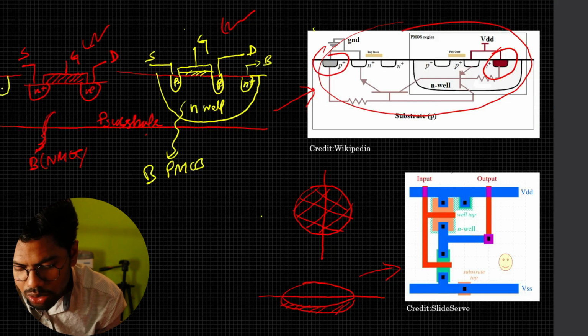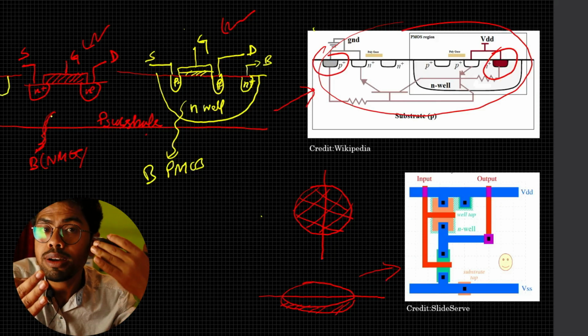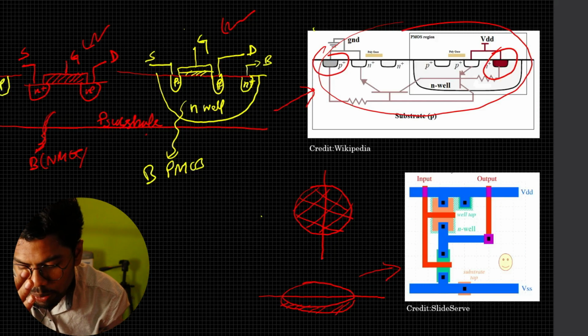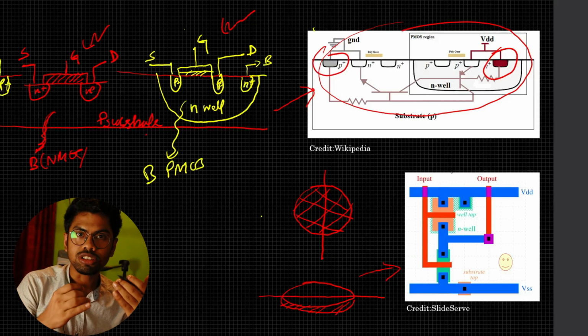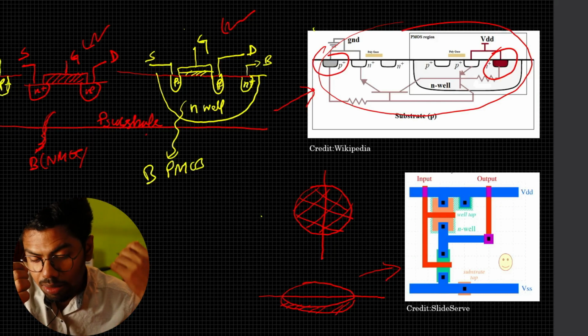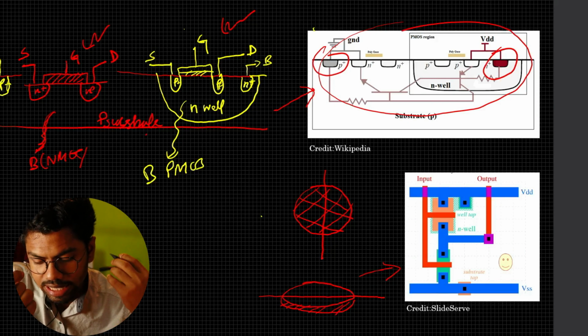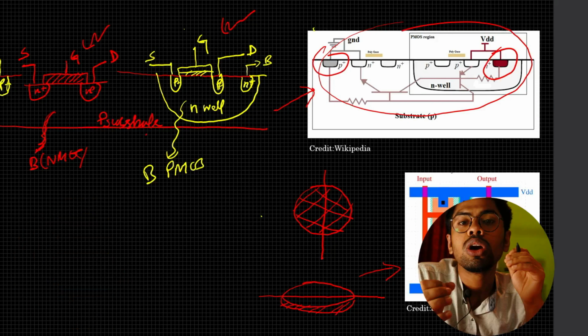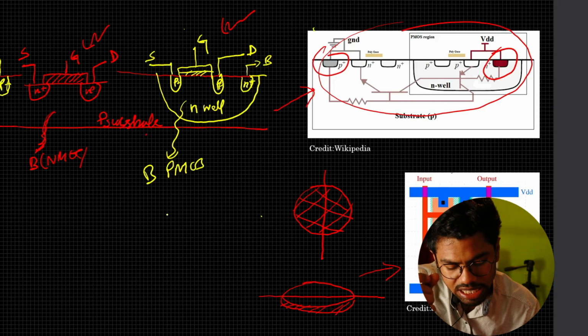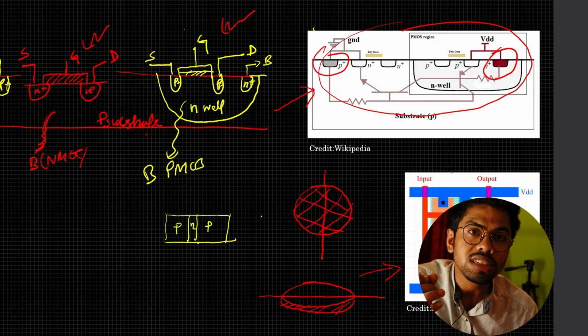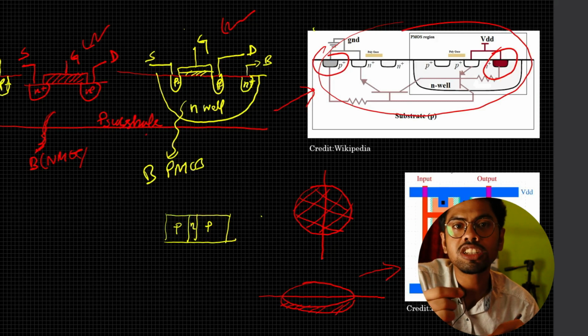And here also we do the same, because NMOS has a P type body, so we do P plus doping here, and we call it the body for our NMOS. Now if you look more closely, you can see one thing: we have some BJT-like structures, because BJTs are nothing but a P type substrate, then we have N, and then we have P. So we call it PNP, and if I reverse it, it could be NPN.